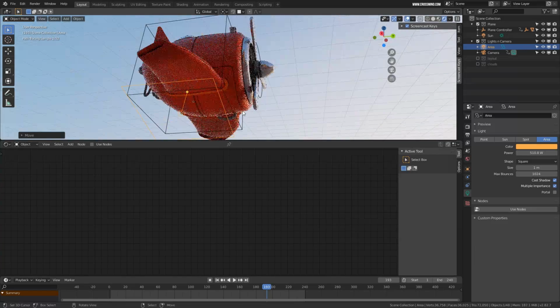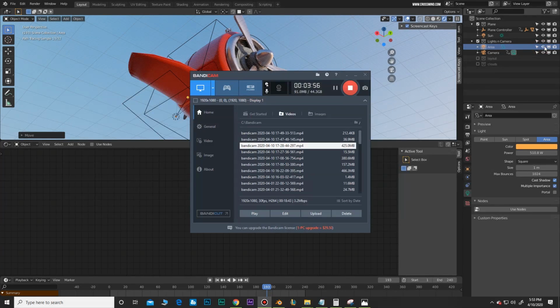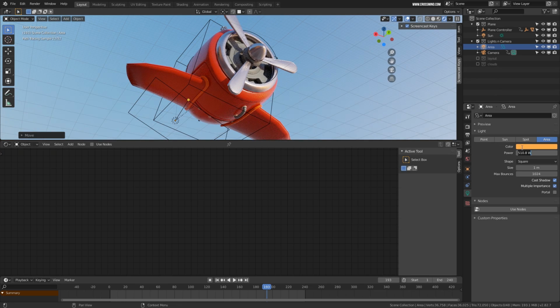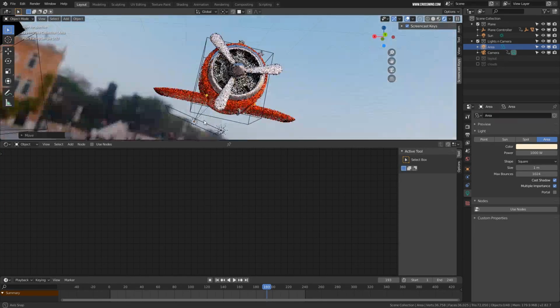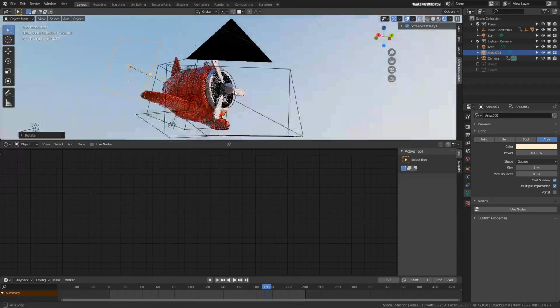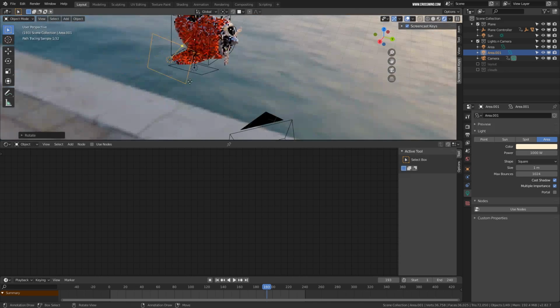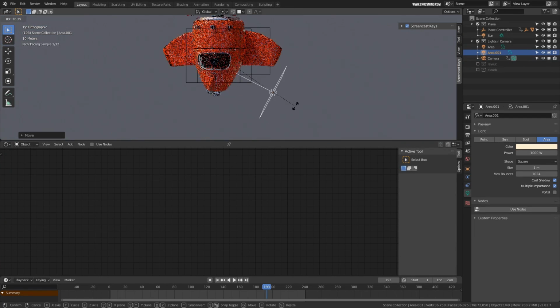so as you can see, when I move this light around, without this it was a very dark looking bottom, and if I enable this one, it looks like a bounce light. So I'll make it 1000 and add some brightness to it. If you want, you can make one more duplicate of this and place it over here so that we have some sort of fill light somewhere over here.